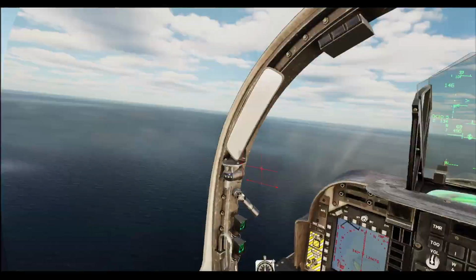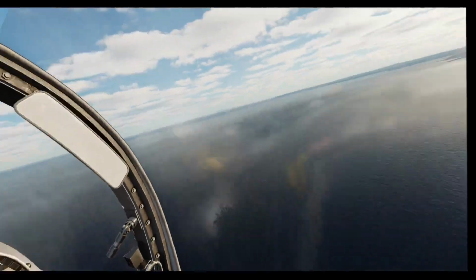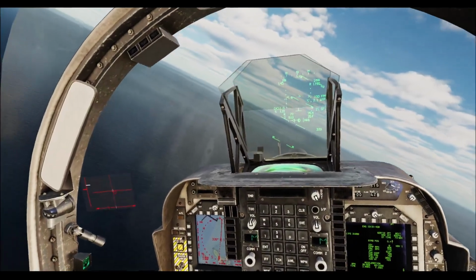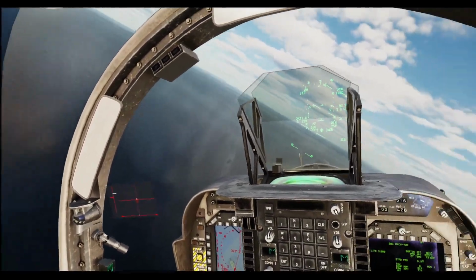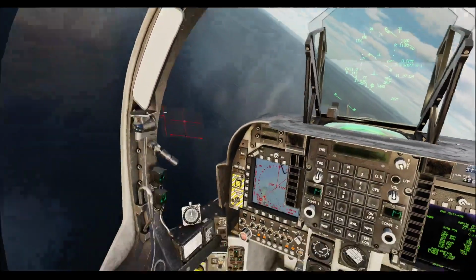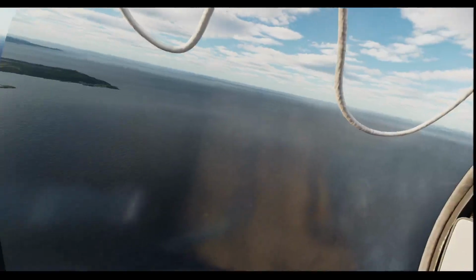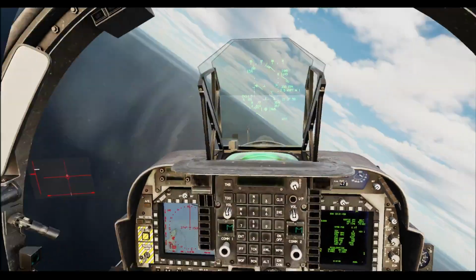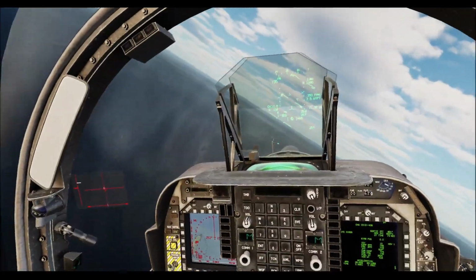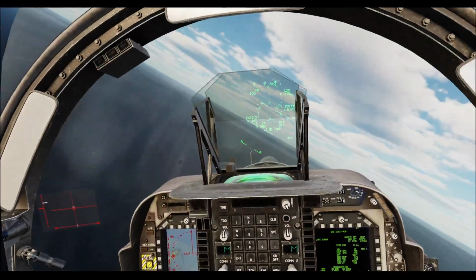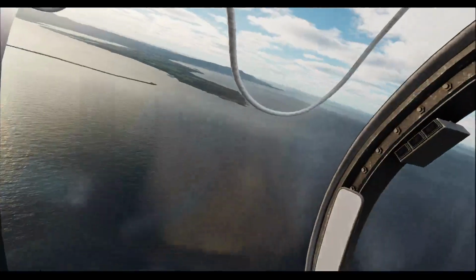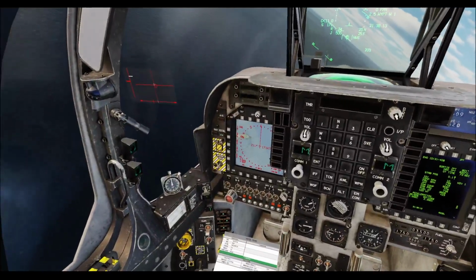Okay, let's start the turn, so a good lookout. And we're clear, let's start the turn. A little bit of extra power to compensate for the lift vector not being directly opposing gravity. 0.1, 0.2, lookout attitude instruments, 0.3, 0.7, bit of rudder to help us get around.